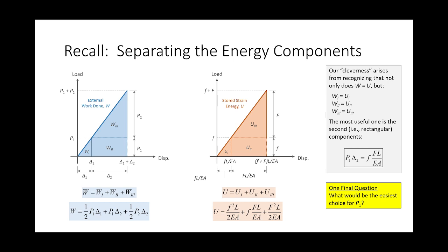And the problem with the bow example of Link drawing the bow and how that relates to structural engineering systems is that typically we have structural systems with a wide assortment of loads. We may have a truss with loads all over the place, and we want the deflection at a particular point. So how do we quantify the energy? Well, the way that we handle that is we apply a virtual load to the structure.